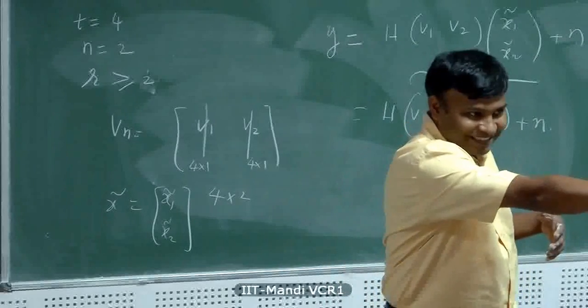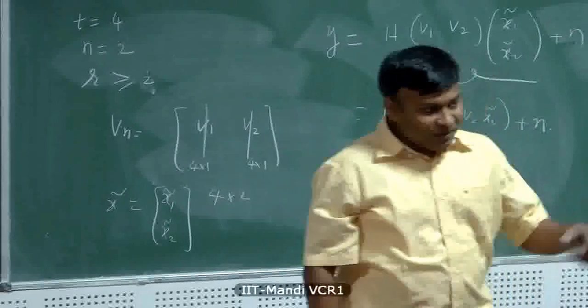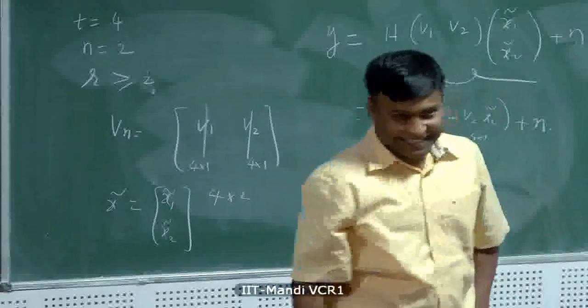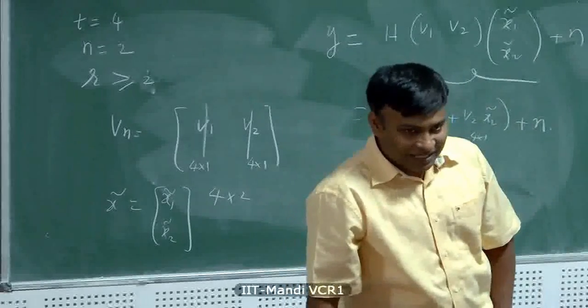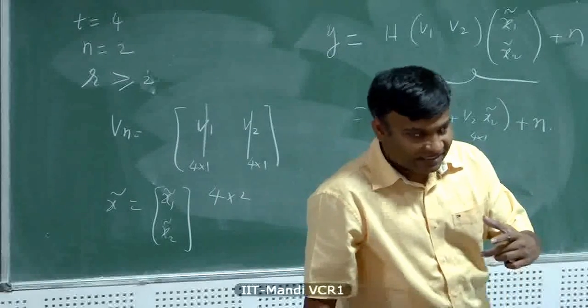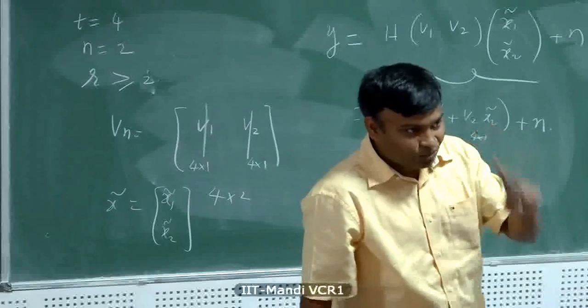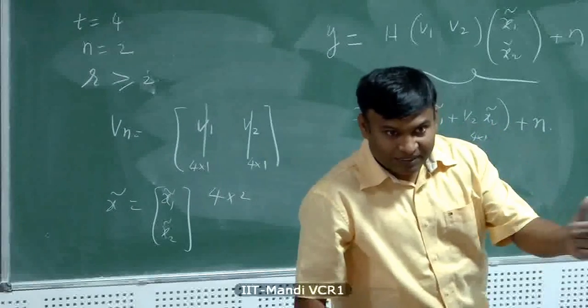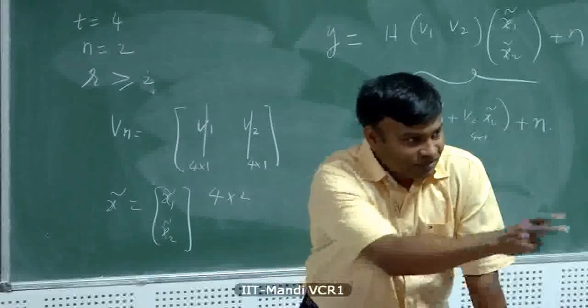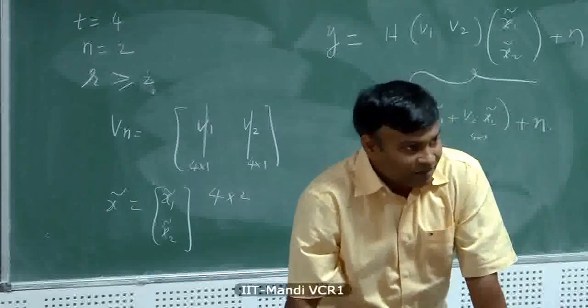I can only put a beam towards one point. If you have two receive antennas, what should I do? Well, I probably put it somewhere in the middle. So your array gain reduces. If you have two transmit, two receive, although you are sending a single stream beamforming, your array gain reduces. The reason is that you can't put a single sharp beam to any one point.